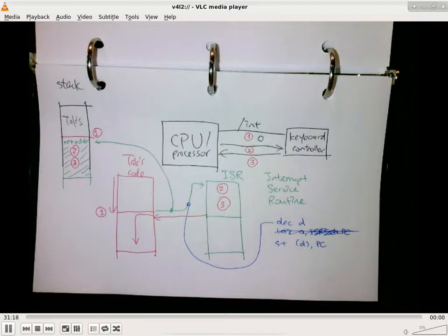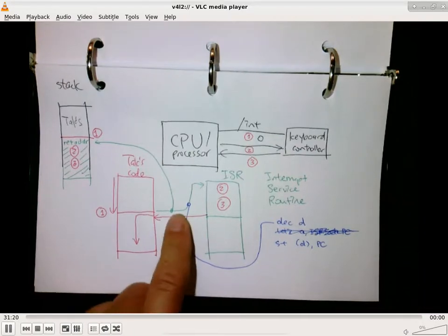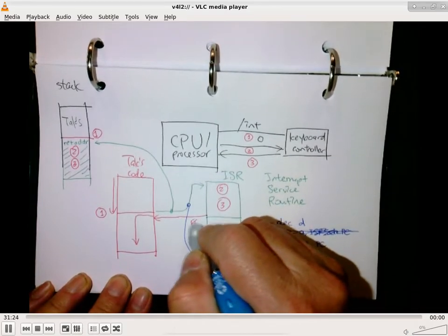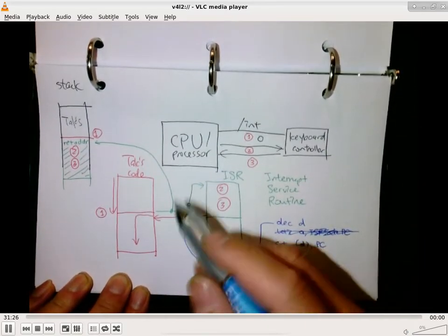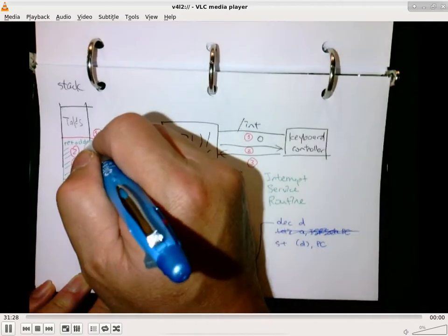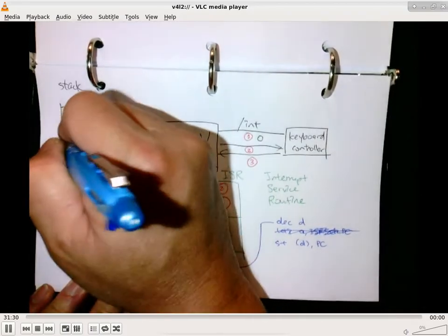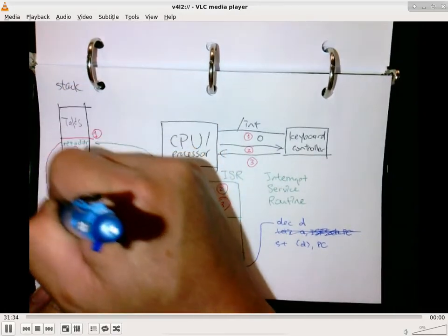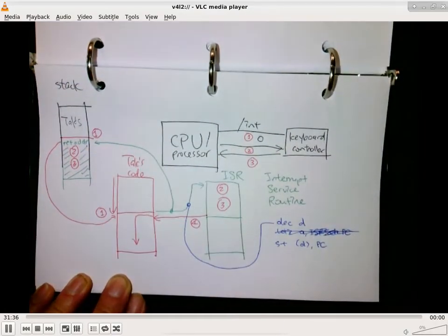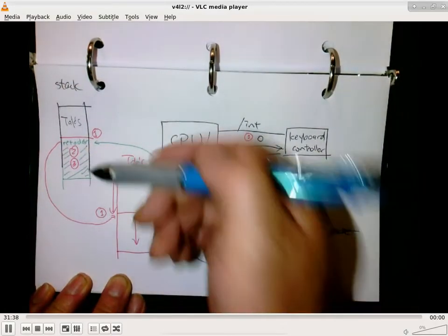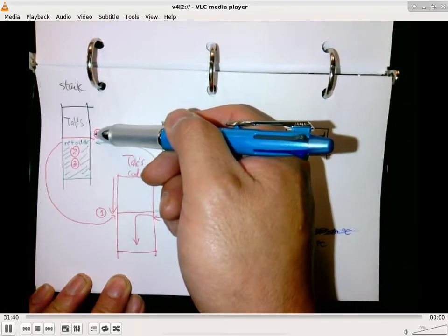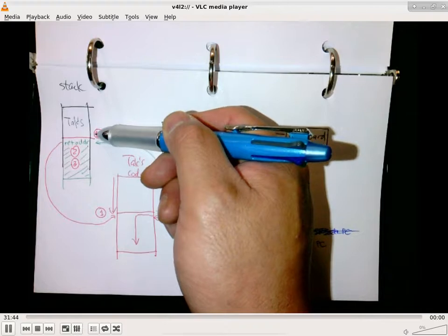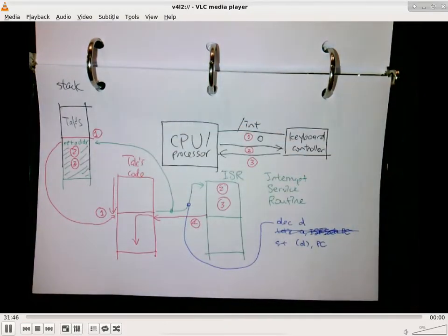When we have the transition back to my code, which is the red arrow here, let's label this one 4. When 4 happens, it is using the return address so that we can now resume execution in my code over here. The stack pointer goes back to wherever it was before my code got interrupted. So from my perspective, nothing got changed.